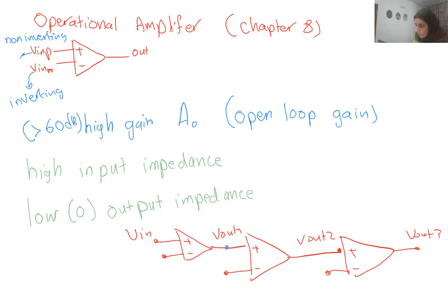If I discuss this second stage, I want to have very large input impedance. If you think of a voltage divider, this is the output impedance of the first stage, Rout1, and assume there is an input impedance Rin2 here, and here I have the Vout1. I want most of the output to be applied at the input of the second stage. So it's kind of a voltage divider.